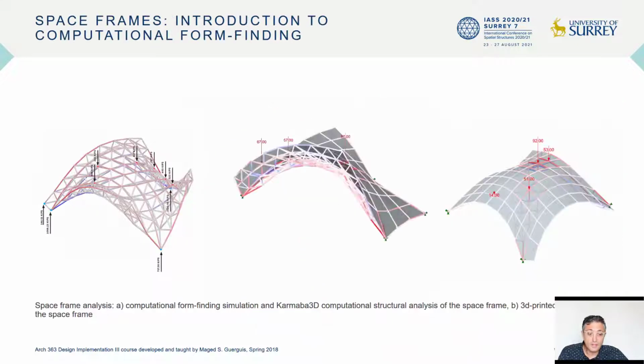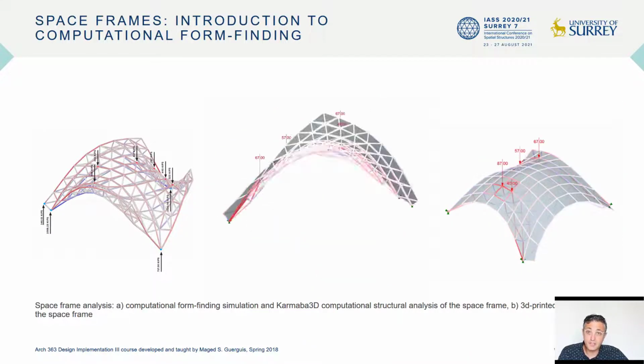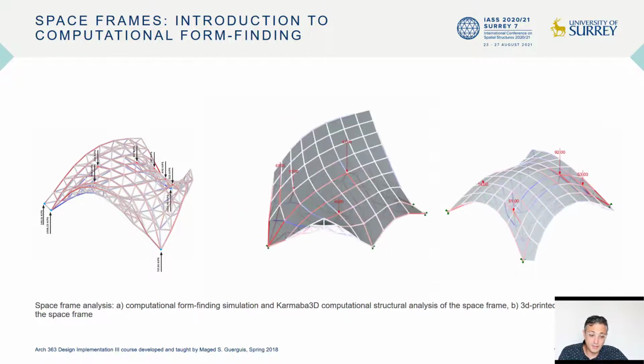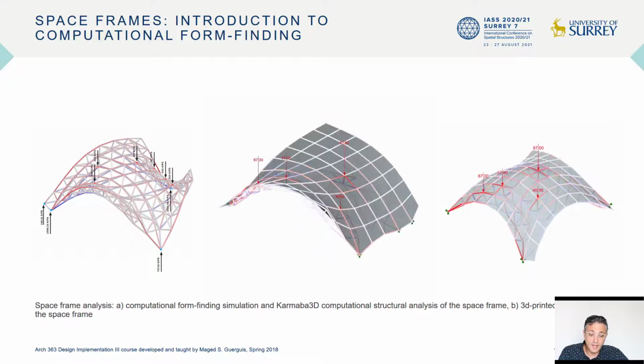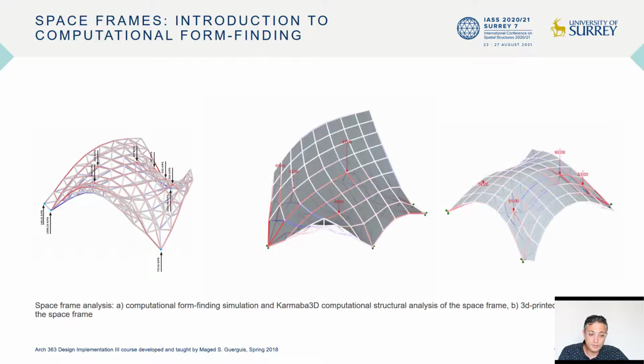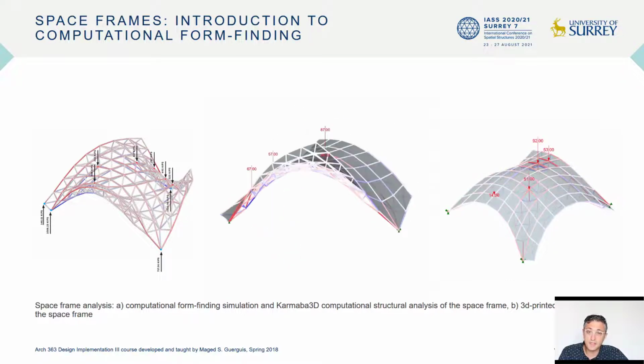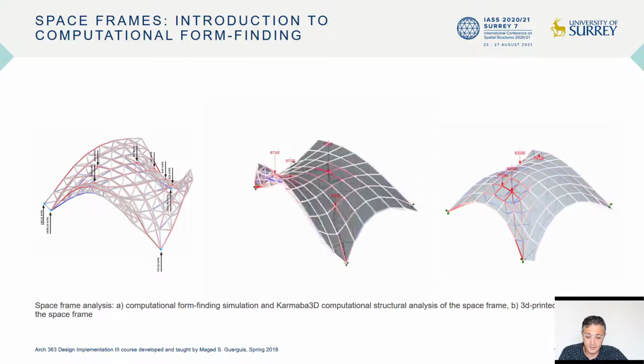The students were introduced later to computational form finding using the Kangaroo Physics Engine. The goal was to create a shell mesh that simulates the behavior of a hanging chain model. With this workflow, students were able to experiment with different space truss configurations, observing the stability of the generated designs and calculating the reactions at the supports.